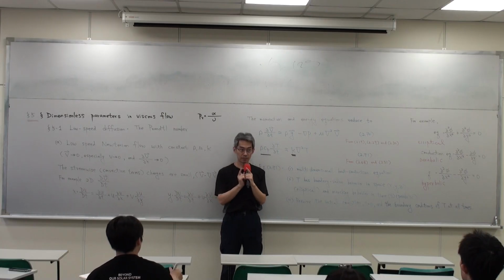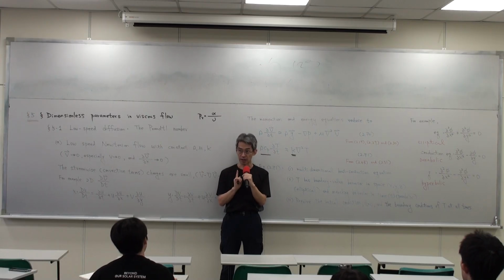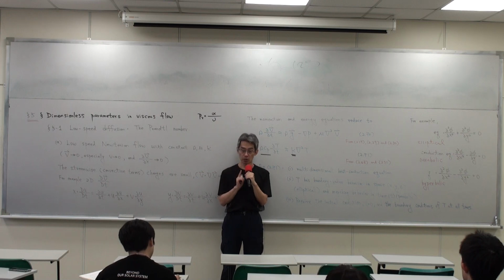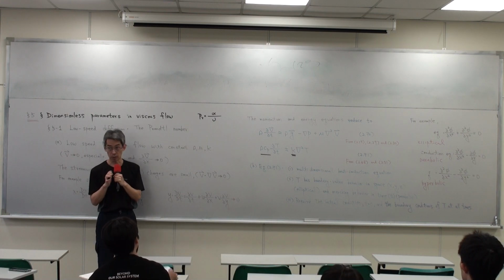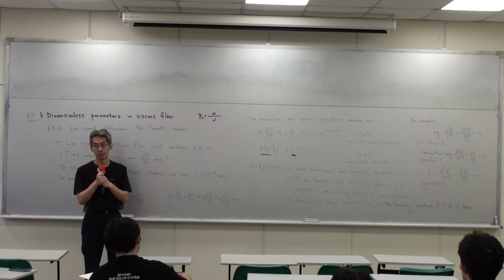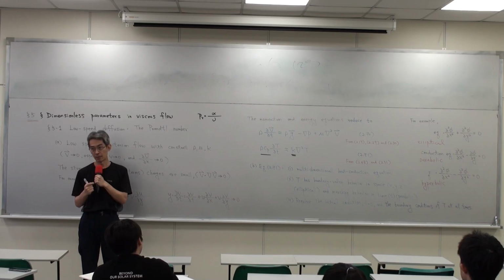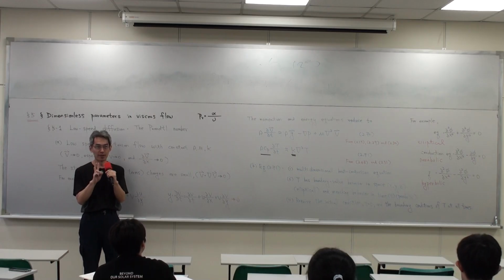And the two diffusion parameters, we want to compare boundary layers. One momentum boundary layer, another thermal boundary layer. So for the Prandtl number, basically, we want to talk about the boundary layer. The reason I talk about this is because the boundary layer is the concept proposed by Prandtl. Okay, so probably you need to connect this together.